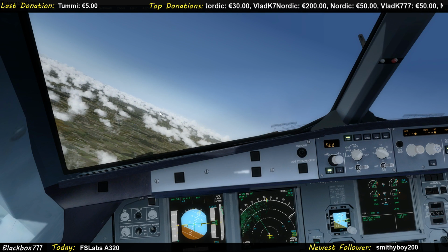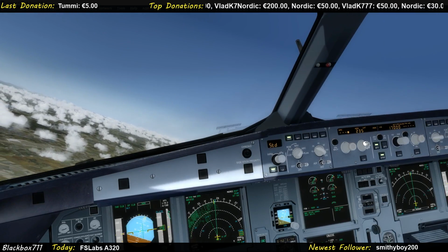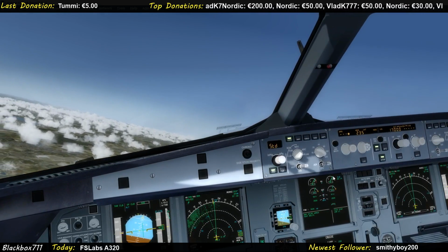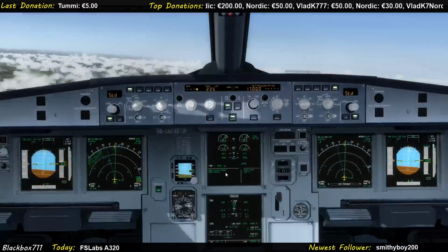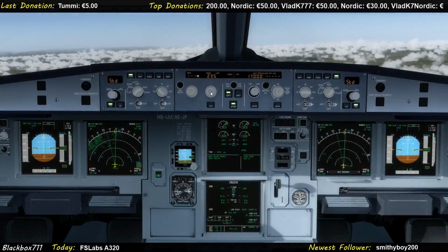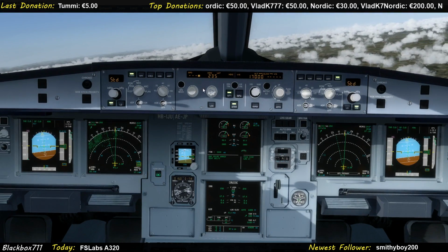So now let's say ATC says, oh, my bad, heading 235. Now, before trying any programming here in the MCDU, the quickest way is just to pull on the heading selector, set the heading. So for short-term manipulation, this is the way to go.